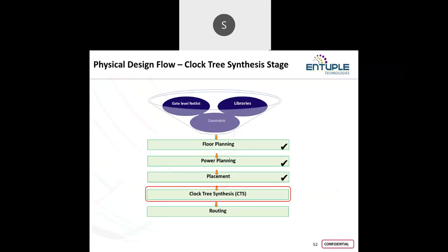Because it is not a human readable format, it will be directly read by the machine, then we send it for fabrication. For the open database, we usually generate it from the in-house tool, in the file extension .enc. So the same way, you can generate the open database also. Usually that option comes into the picture when I am going with mixed signal. For example, I have some analog blocks in the design and I am going with the digital part also. When I combine both, that is when the open database comes into the picture.